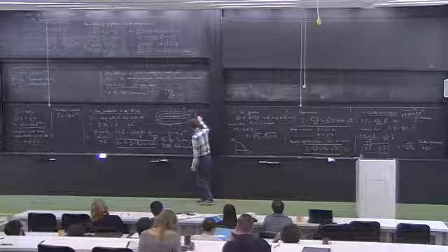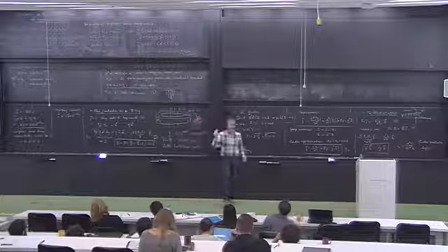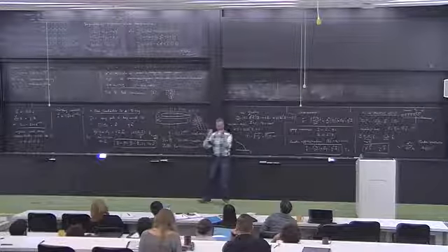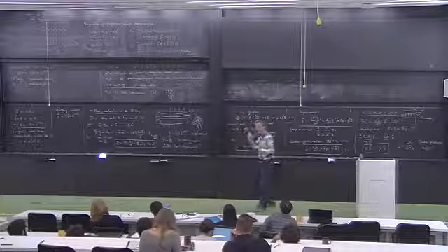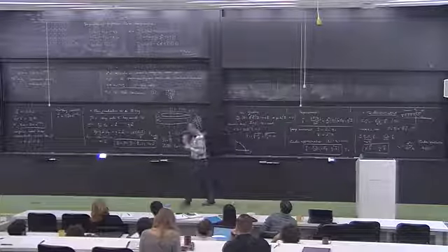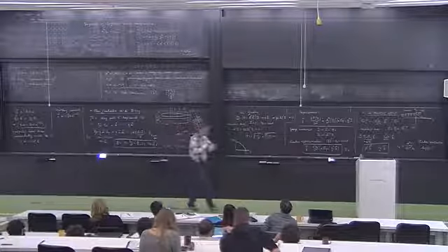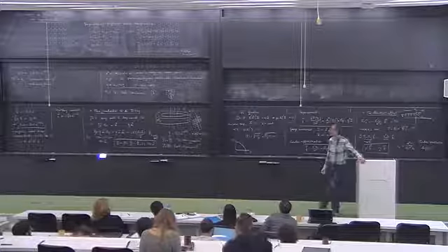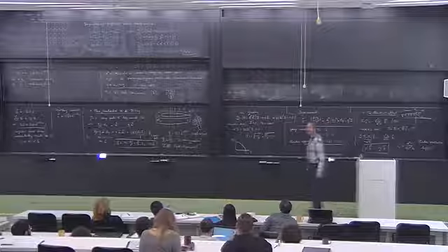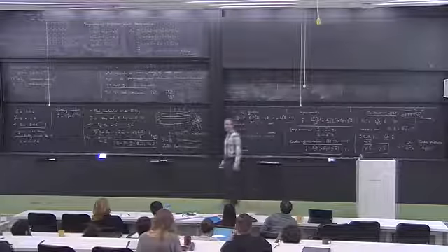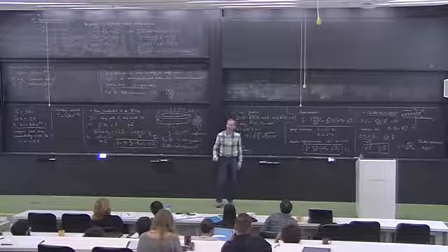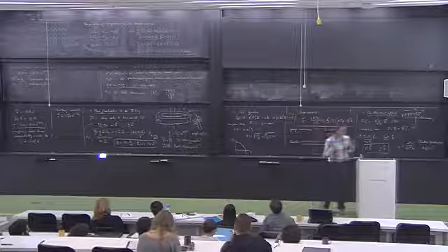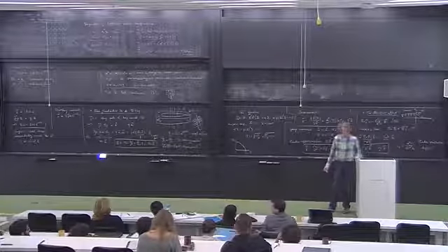But imagine one part of this material went normal, so all this current has no place to go. What then happens is that the whole wire slowly goes into the normal state and suddenly has resistance. All this current is now too big to sustain in a non-superconducting wire, so it all melts, and basically it just goes kaboom. So that's not good. I actually saw somebody's lab after a superconducting magnet did this. There was nobody in it, fortunately, but it looked literally like a grenade went off there. The lab was kind of ruined.